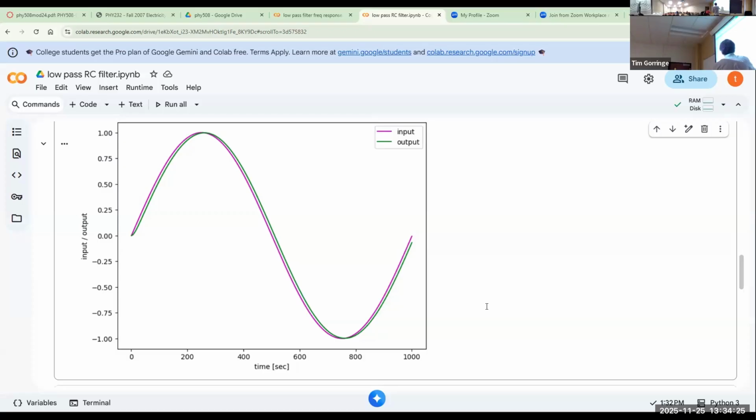And we see this here. Look, the amplitude of the output is just fractionally lower than the input. The phase of the output is just fractionally delayed. It lags the input. And that tiny change is arising from the feedback that's in a filter.